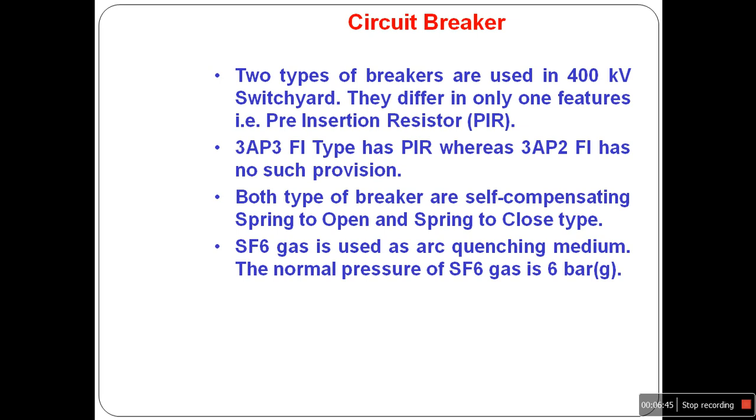Mostly the circuit breakers used in 400 kV switchyard are spring to open and spring to close type, but it may not happen in all cases. Some circuit breakers used in 400 kV switchyard are hydraulically operated, but I am just telling you one case which is used mostly in modern power systems.